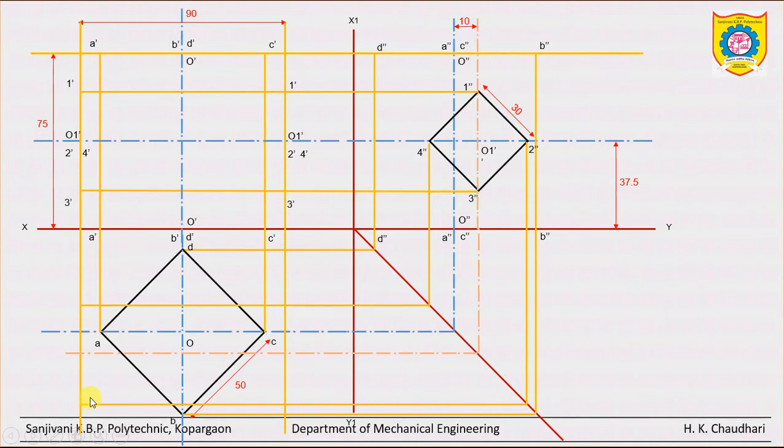Turn it into the front top view. Now we can label the points where this projection intersects the surfaces. These are the surfaces: AB rectangular face, BC rectangular face, similarly CD rectangular face, and DA.